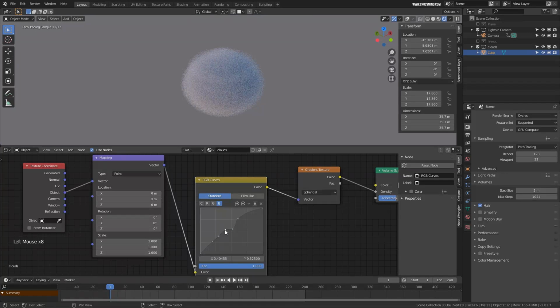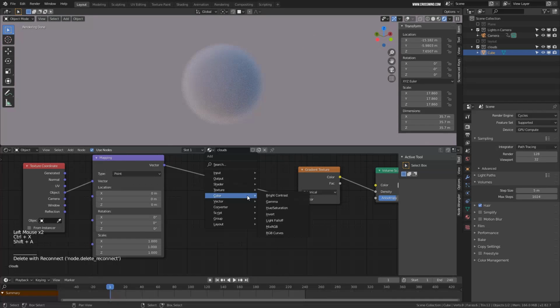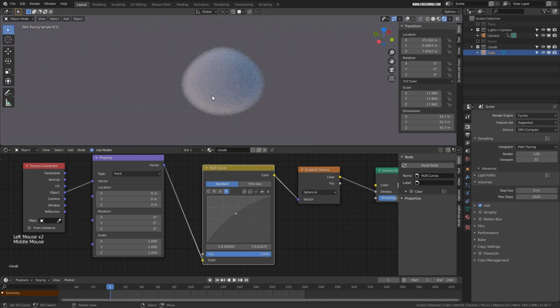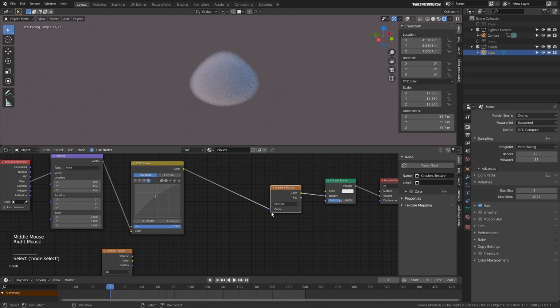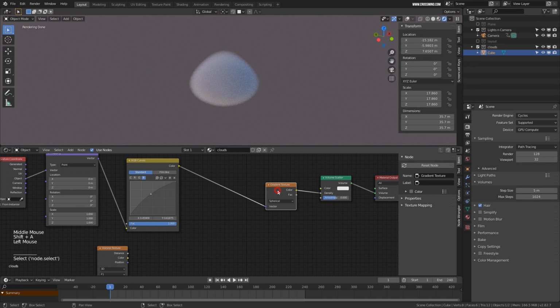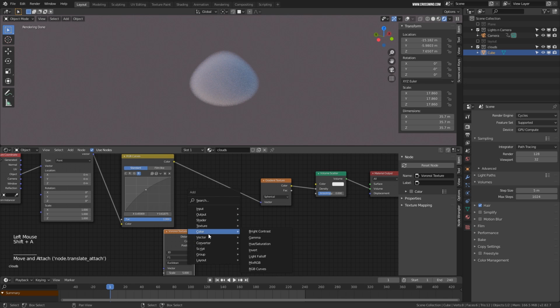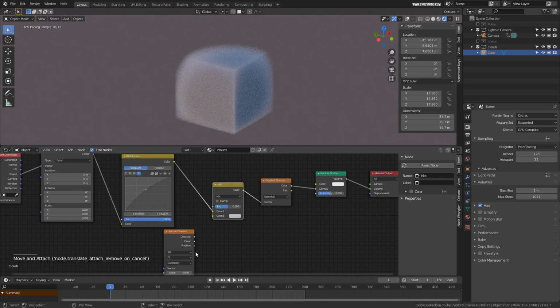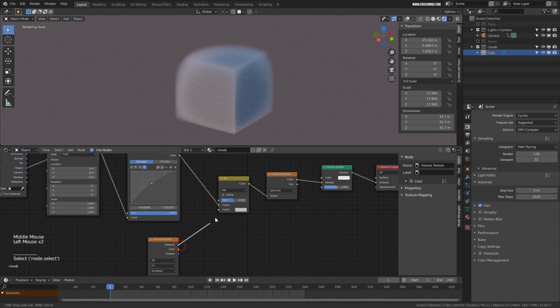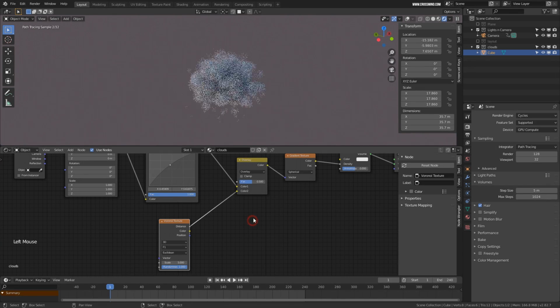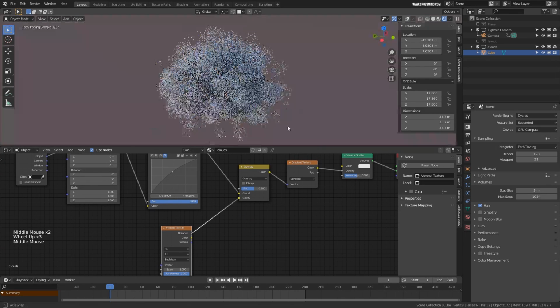And this is not just it. We are going to create one interesting texture just in a moment. Now I'll just reset it, RGB curves, blue, and I just want to give this one a slight shape like this. Okay, and just like in the shading chapter, we had discussed how you can combine multiple textures. Now this gradient texture, we can multiply this with a Voronoi texture. Now let's go to the color and click on Mix RGB and bring in one Mix RGB and plug the distance of Voronoi texture into this one and change this to overlay. And now you can see you have a cloudy looking shape.